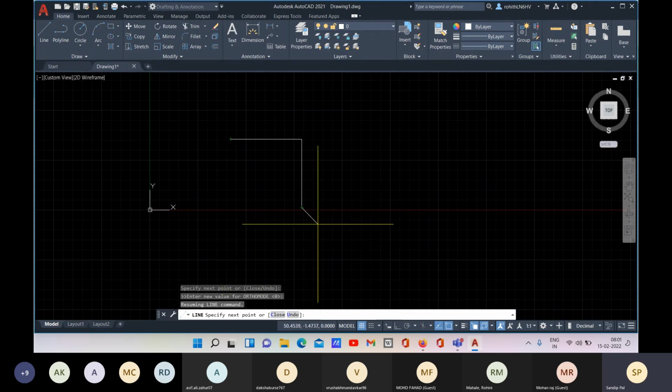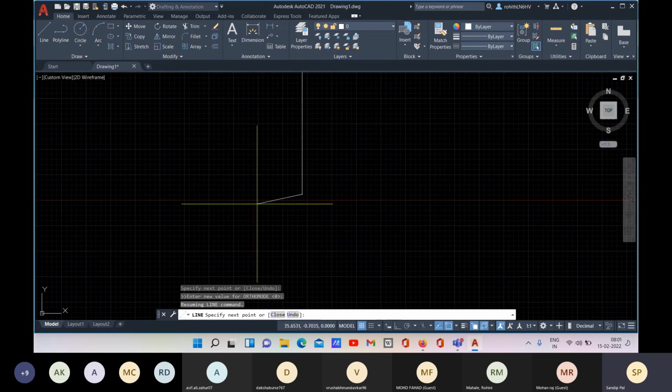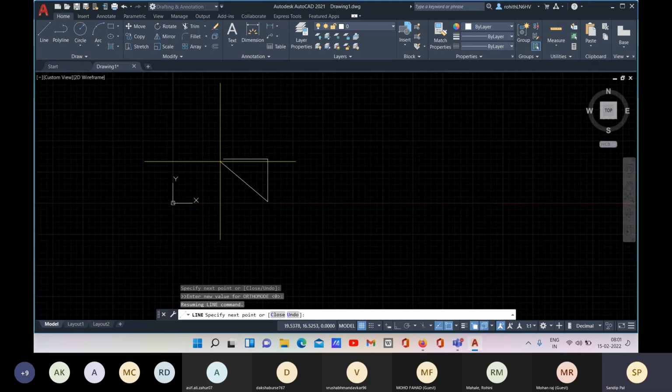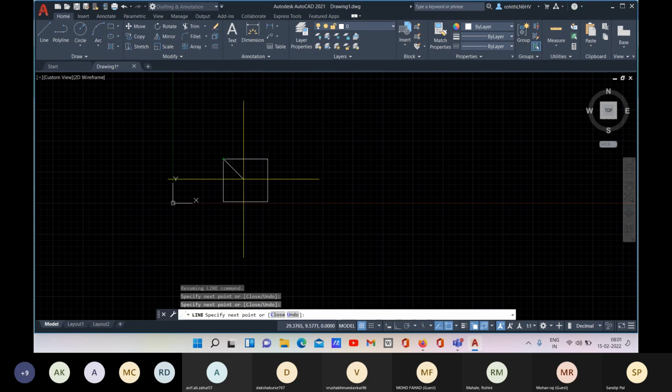With the help of F11, when you are activating it, you see that green mark on this snap point. When I place my mouse pointer so that it will be tracked, this green mark is showing, and the green mark is showing here. Then these two object snaps will be tracked, and now you can click on it. All right, and we have F12.